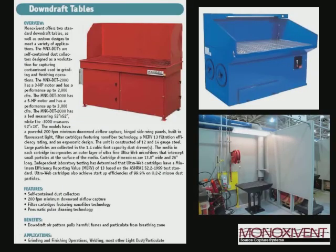Now, these are our round tables. Typically, the capture velocity is 150 to 200 feet per minute. Basically, you take your table size times your capture velocity. So in the case of the bottom right, you have a 3-foot wide table by 2 foot deep, equals 6 square feet, times your 200 feet per minute capture velocity. You're going to be at 1,200 CFM for that particular unit.